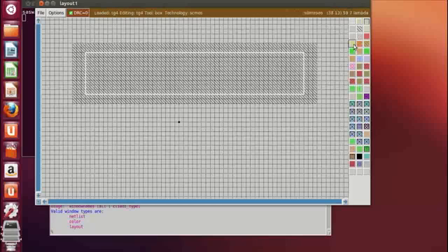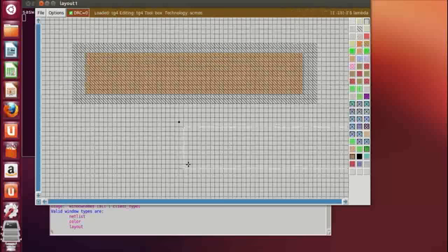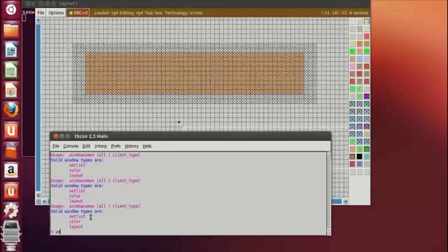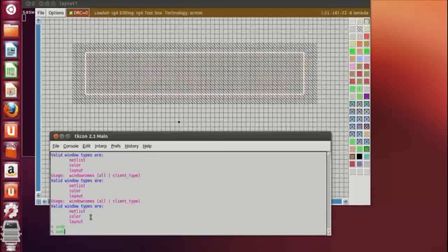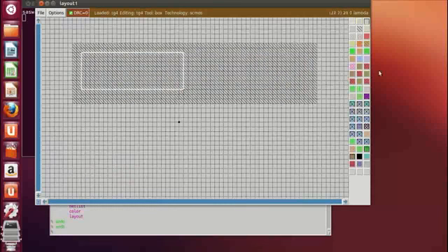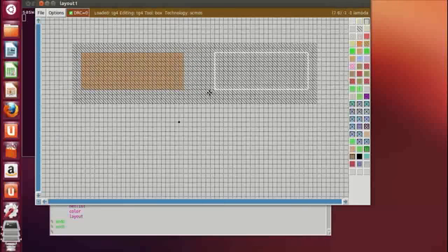Now take the portion. The area will be painted with a P diffusion, so have to search for P diffusion. This is my P diffusion. Press the middle key. Okay. I can undo. I have to select this portion and then the P diffusion. P diffusion. Now if I want to extend this, okay, now they're looking equal.